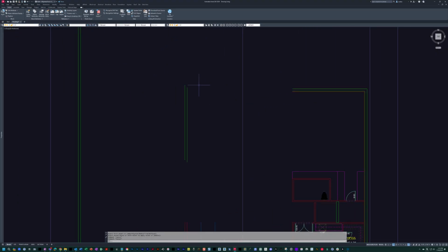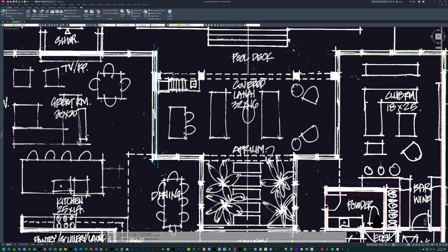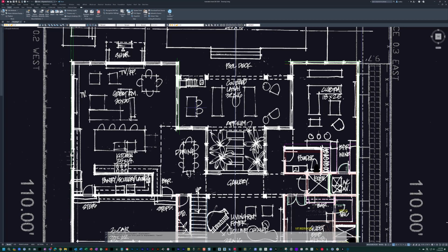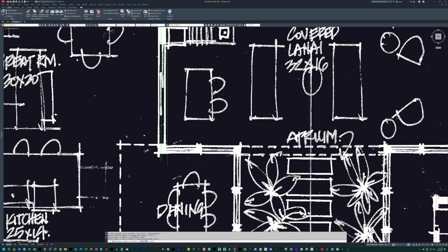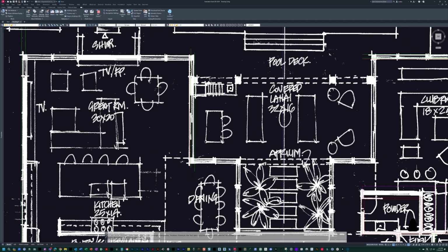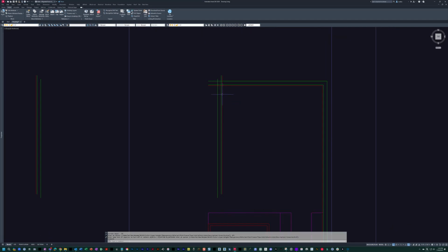All right, and then turn back on, and we know that this wall, if you remember, we talked about this wall aligning with this garage wall. This wall is obviously going to be centered around this wall to create this wall. So let's mirror this and see what happens. I think that could be nice. In fact, I'm just going to offset 2 inches this way, so I only have to draw it once. I like doing things one time, and because now if I mirror this about here, that just gave us that wall.